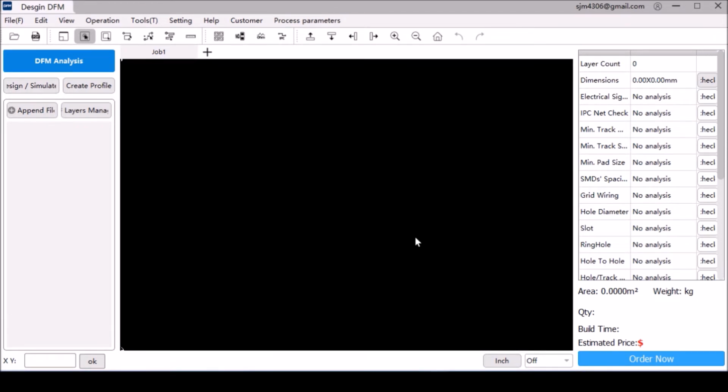checking software. If there are any problems that pop up during any of the previous three steps, then I go back to the PCB editor, I fix them, and then I rerun the checks all over again. Once the board has passed all of these steps, I can be fairly confident that there aren't going to be any major problems with the board itself, and I can freely place the order at that point.